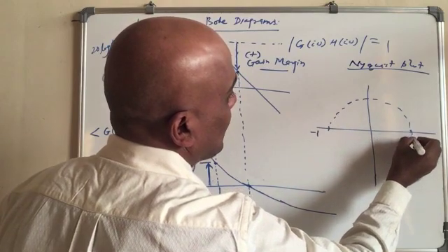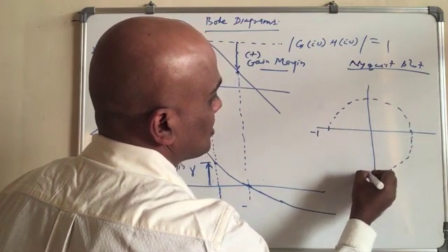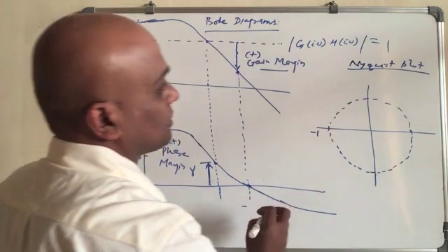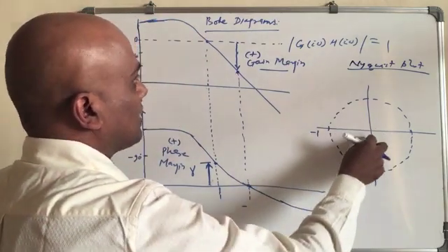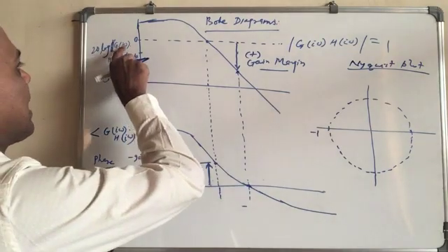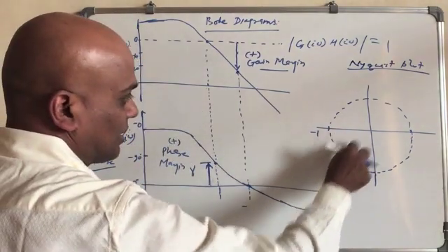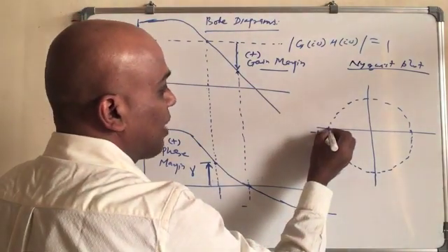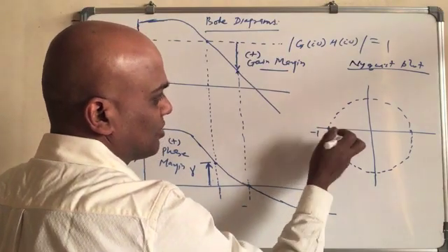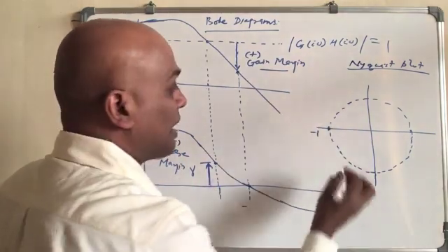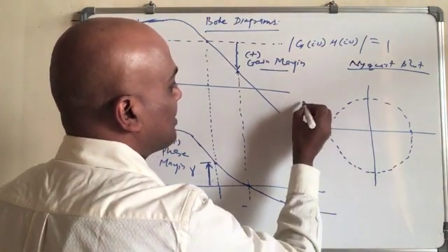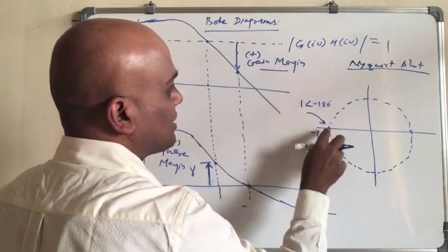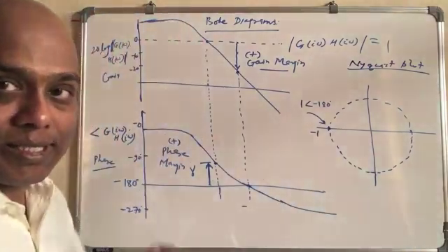So we know that the radius in the Nyquist diagram denotes the gain, or the magnitude of G, right? So the magnitude of G(iω) times H(iω) is what the radius is. Okay, so this point refers to minus 180 degrees, right? This point is the one which has gain 1 and angle minus 180 degrees. That's our reference, and from here we are going to measure.